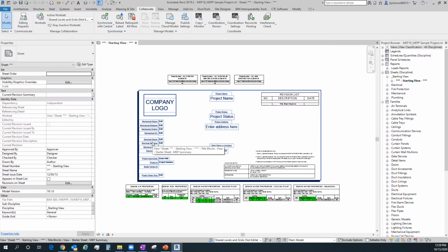And if you do an entire building layout with room bounding lines, then that's room separation lines. That would be an area of concern to go do a massive cleanup at some point. Make sure you know which view those were created in, hopefully a named view. They would have those names in them. And then be able to wipe those out or do some sort of a quick select that would let me see them directly. And we do actually have a tool for that as well.